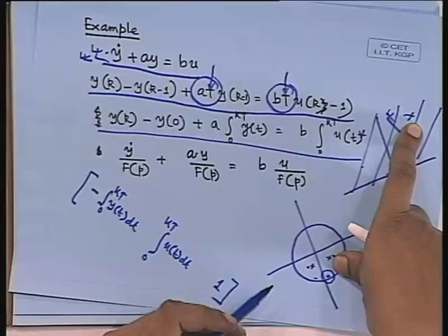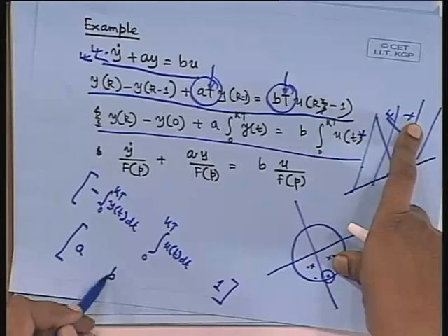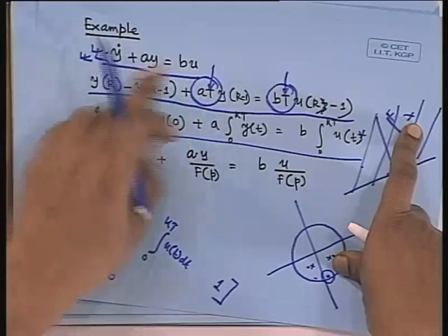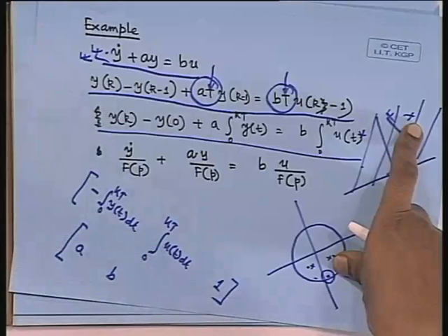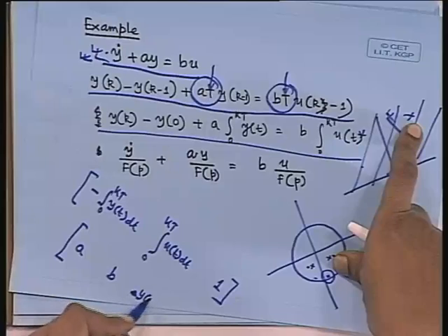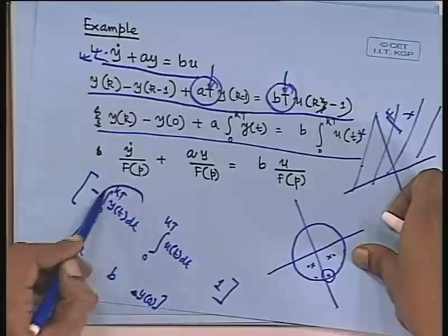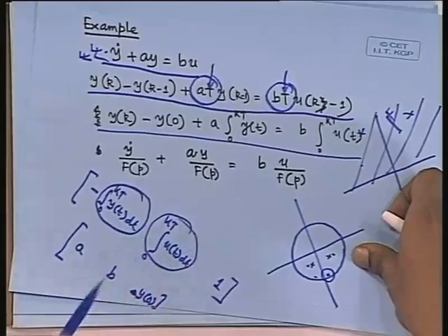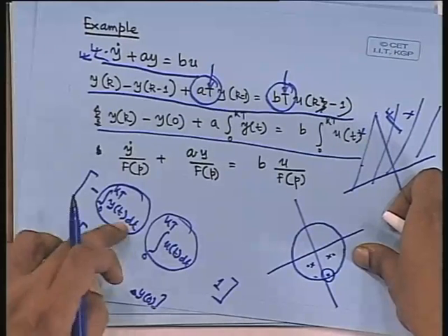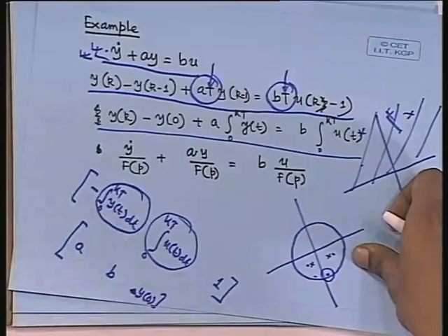And then what parameters will you get? You will get a, you will get b, which are the same as your continuous parameters, which do not depend on T, do not suffer from that problem, and y0. So you will also estimate an initial condition. See, this you can very well compute using sample data. What's the problem? No problem. If your sampling time is faster, this estimation will go better, because your signals will be more accurate.